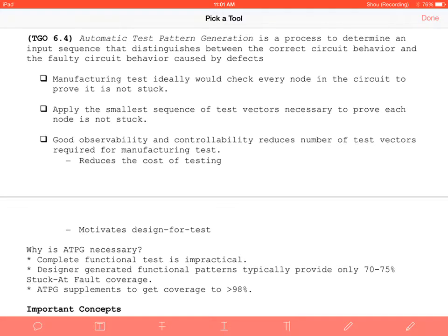So, in the last lecture, we briefly talked about these concepts of testing, how you use the 5-step troubleshooting method to be able to break down a circuit and find circuits where you have more than one fault. Some fundamental things to remember, particularly taking the details at each node and figuring out if you're able to propagate the error to a certain point to the output, or if it stops at a certain point, and therefore you can act and make sure that you've covered the whole circuit, so therefore you can accurately determine whether or not there's more than one fault.